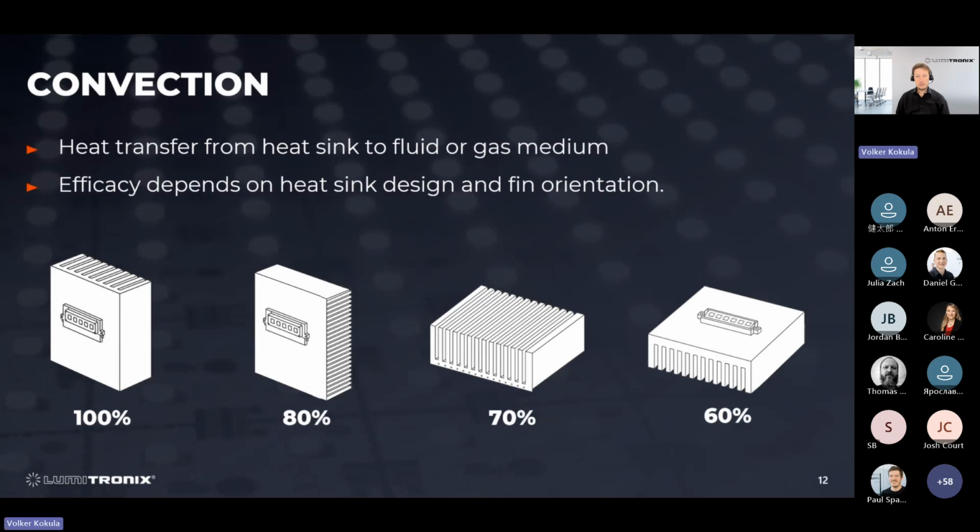What you have to keep in mind here is that the design of the heatsink can have a huge impact on the efficacy of the heat transfer. Not only the design, like how the fins are made up, but also the orientation of the heatsink. So you need to understand the application your light source will be used in order to make the most of the heatsink you are adding to your product.